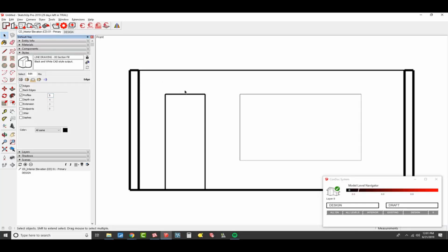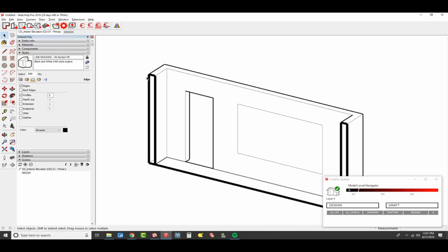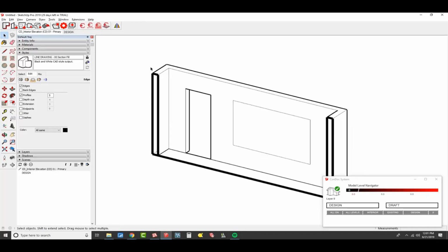So let's look at what we've got going on. In SketchUp, in the style, these are multipliers. These aren't line weights. They're just multipliers. They don't mean anything until they get into layout. So the multipliers that I've set up on this specific style, my profiles, anything that defines space beyond, is going to have a 5 multiplier. When there's space beyond, it's those old drafting techniques where you thicken up the lines to give that drawing a little bit more pop. That's what's happening here. I've got a 5 assigned to my profiles, and then when I look at my section cuts, my section line width, those are set to 10.